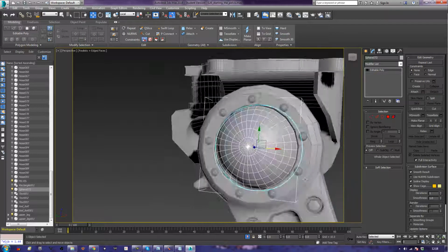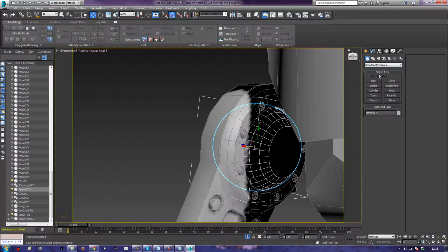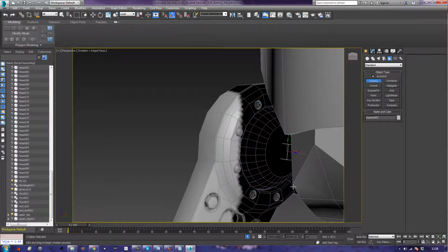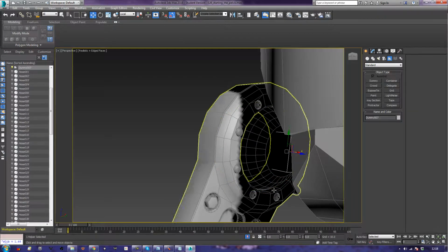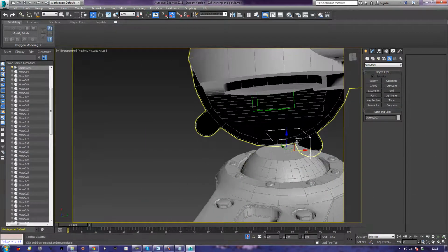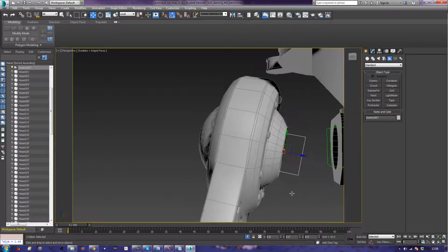What I can do is just double click this edge and delete, and that'll leave this little island just floating here. And what I can do is grab this and cap it like that, and that gives us that shape there. Now what I'm going to do is again just make a dummy, and just going to try and work out where the middle is. The good thing is that I can adjust this if I need to, so sometimes using the artist's eye, as you can see, doesn't quite line it up as well as you hoped. Put that there, and then have a look at this. You can see this isn't quite right. There we go. So we've got these two dummies here and here, okay?